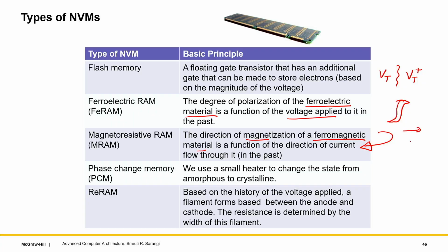So basically for the magnetization, there are two states, a parallel state where one layer has a pinned magnetization and the other's magnetization can be changed. And MRAM also, the spin torque transfer MRAM, is the most popular today. Let me write it, STT MRAM. And there the idea is you look at the magnetization, so parallel, anti-parallel. So this is very popular. Phase change memory is also quite popular.